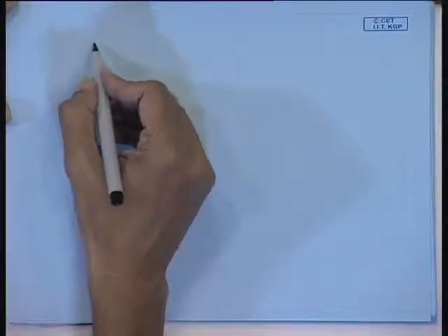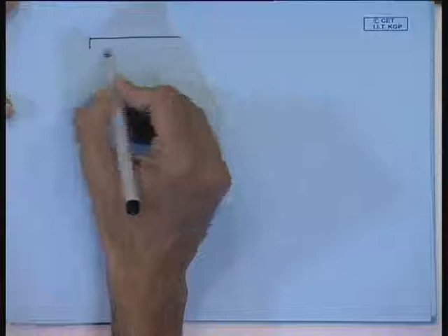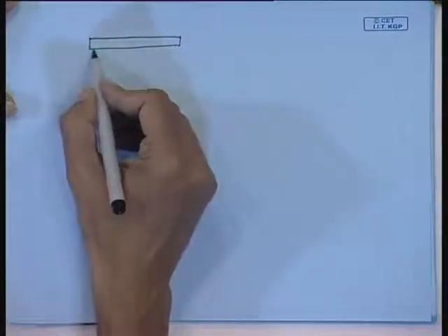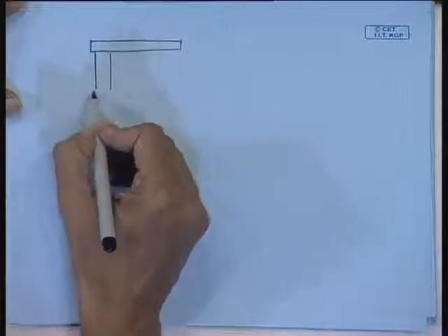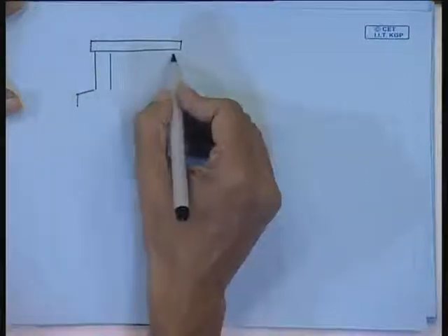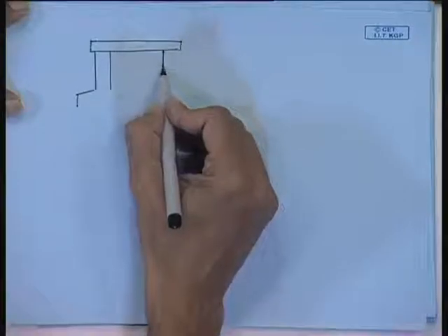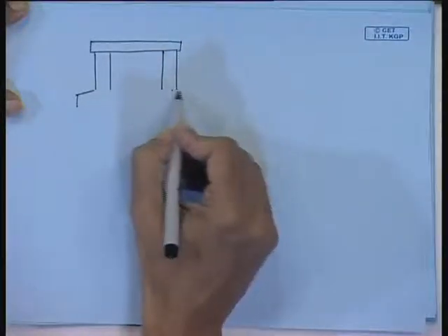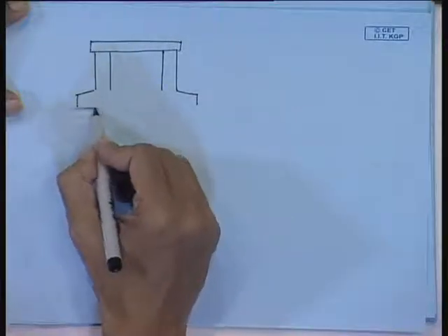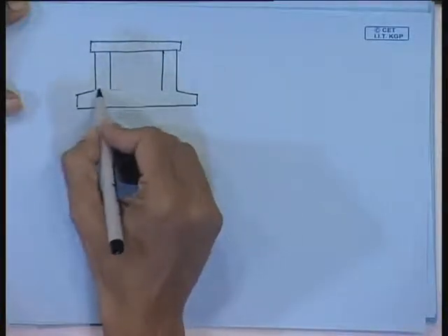Now, coming to the hydrodynamics. So, you will find the various configurations of your TLP, the one that I have drawn. Now, you can extend your TLP, the pontoons. So, pontoon configuration can also be like this. So, these are called extended leg TLPs.